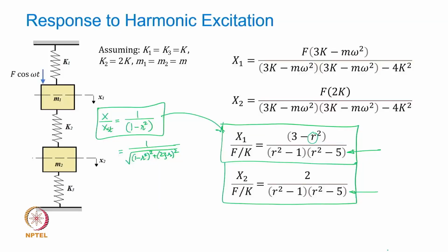Relative to the other frequencies, they will reach their maximum value. Of course, in some cases, depending upon the mode shape, some amplitudes will be 0, some of the masses will simply not move. We have seen the node position, but the resonance applies to every mass element in that multi degree of freedom system.